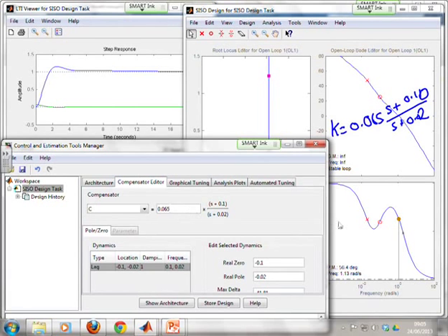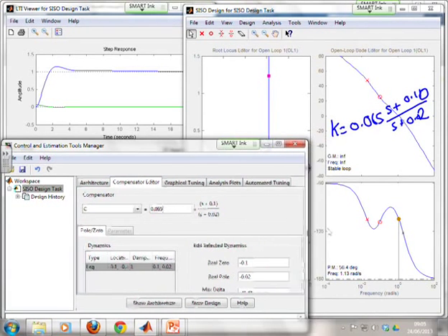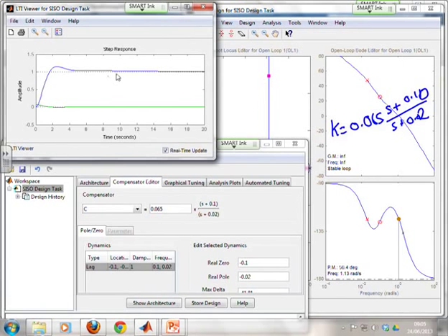And what do you notice after we've put the lag compensator in? You can see we've got 56 degree phase margin, so about 5 degrees worth lost from the 60 we started from, which is roughly what we expected. And you can see this classic phase dip which you get from the lag, but it's to the left, so it doesn't worry you too much. And there you can see the closed loop response. Now here it's worth noting, can you see this very slow mode that comes from this lag compensator? If you had a simple gain design you wouldn't have this very slow mode gradually settling, and we'll look at that again when we go back to the MATLAB window.